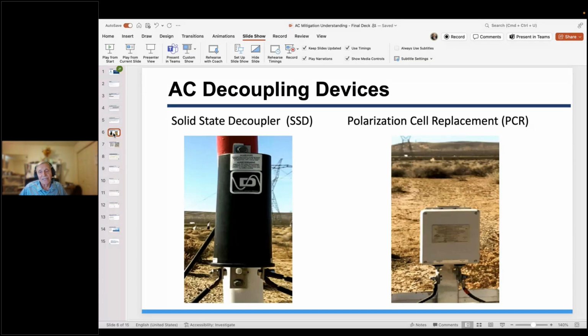Most of it is lightning, and remember, the sizing of your cables also needs to be done based on where you're located, but it's instantaneous. So this is why we're using these decouplers. Now the decouplers are used both for steady state, to drain the induced AC voltages and currents, and they're also used for faults. And we're going to discuss that in a few minutes. The next slide.